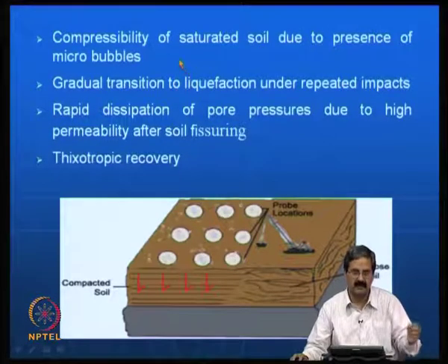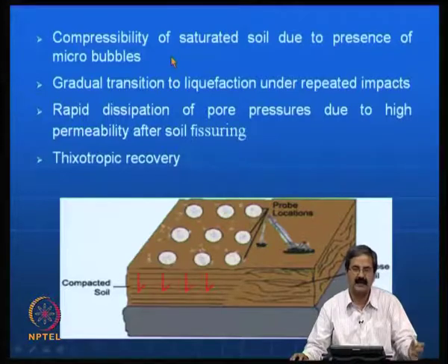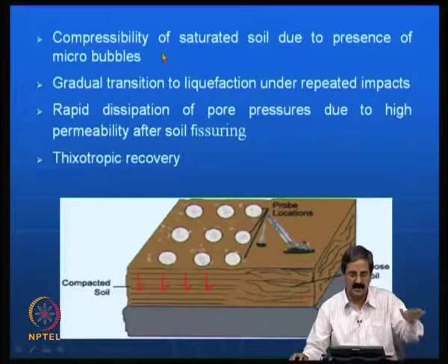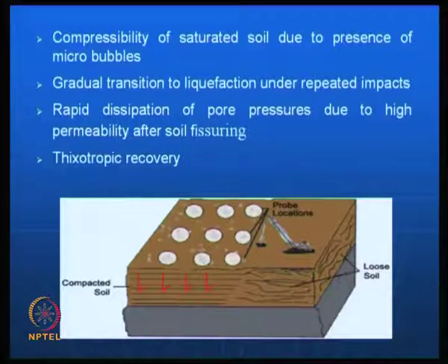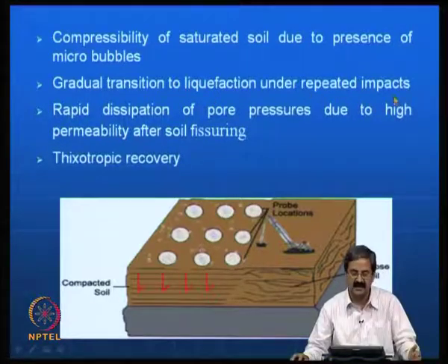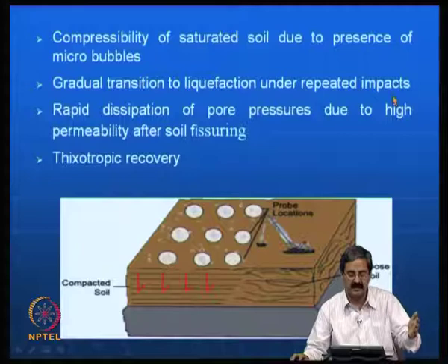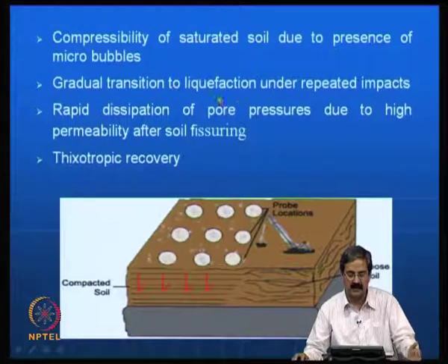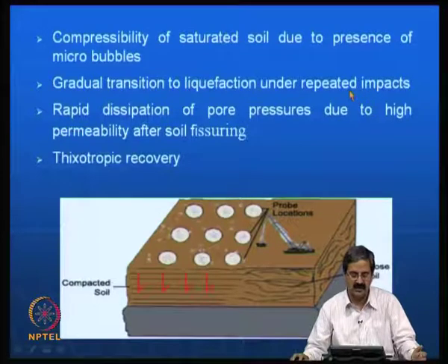Bubbles are there at micro level, small bubbles that can get removed, and then the saturated soil gets consolidated. Then there is a gradual transition to liquefaction and repeated impacts. In fact, there is a tendency of high pore pressure mobilization because of repeated impacts, and if you allow the pore pressures developed because of the repeated loads to dissipate, then the process of consolidation is okay.